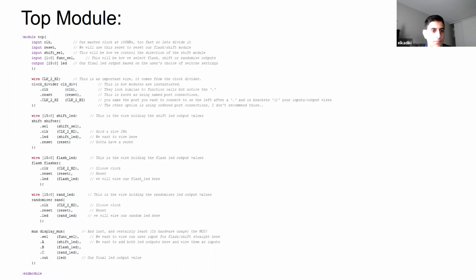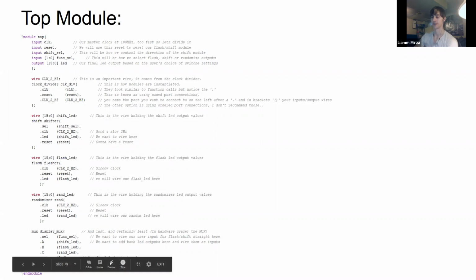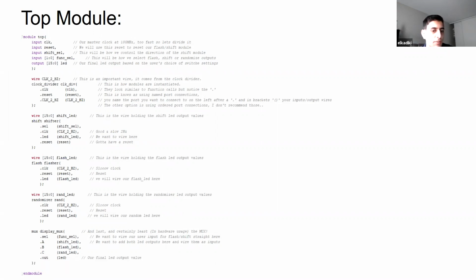And you can also see here with the mux declaration that it doesn't specify what the parameter is, so it will default to 16. But if you wanted it to be something different, like a 12-bit mux, then you would use the pound symbol and then put 15 in there. Yep, right before the first bracket open. You can pass in a 15, or maybe a 12. I meant 12 for a 12-bit mux. I don't know why I said 15. Well, 15's right. I mean, right now it's 16 bits, so.